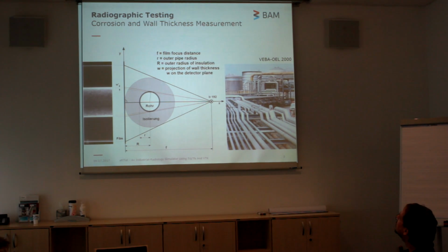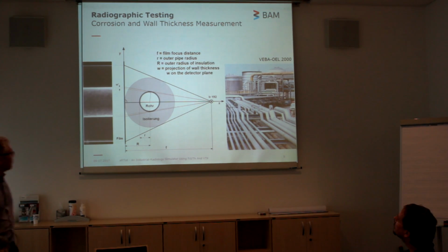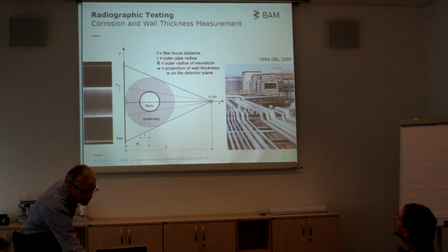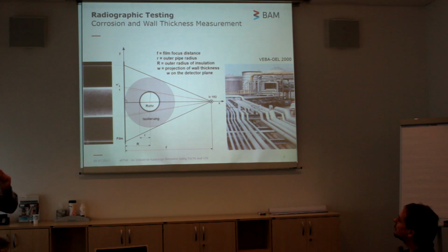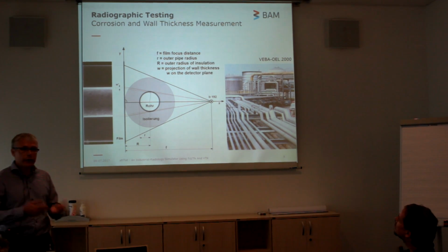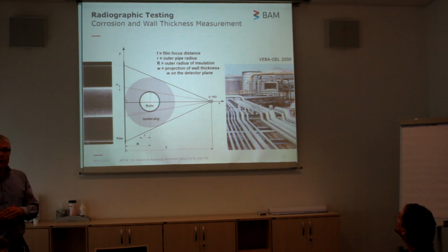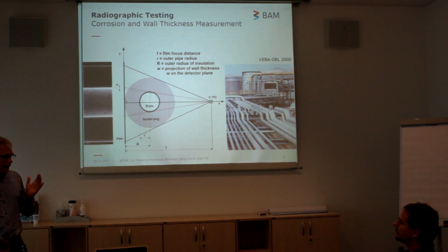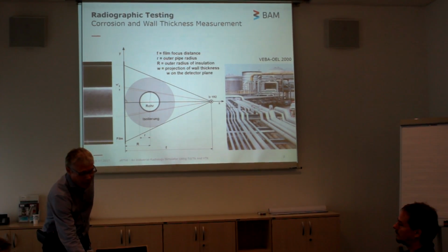Here in a chemical plant, probably isolated pipes, but with radiography you can test it without removing the isolation, and it is about looking for corrosion and wall thickness measurement to look for the integrity of the installations. So that is all about non-destructive testing. That's the field we are working in. So we want to test the components without destroying them, so they should be in use afterwards.